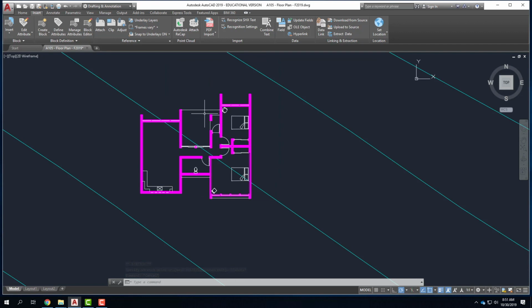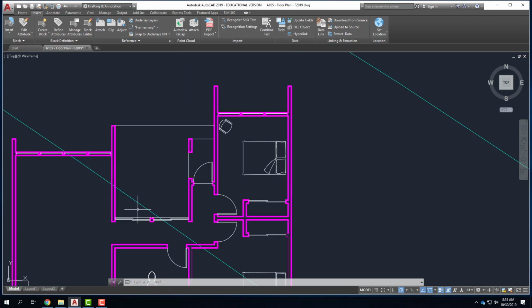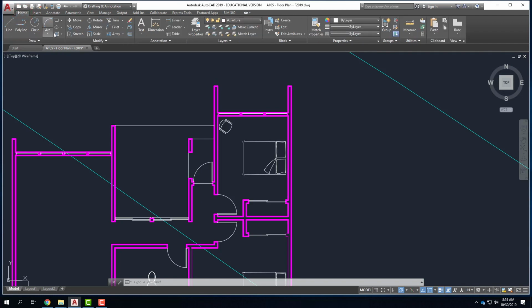The last thing that I want to show you is that you can also use hatches to do things like what the flooring would look like or what have you. I've included this part 3 as optional because depending on what blocks you have in your space, it may or may not be an effective method. To do that, we're going to use a tool called the Hatch tool. It's available right here in my home ribbon. So I'll click on Hatch.